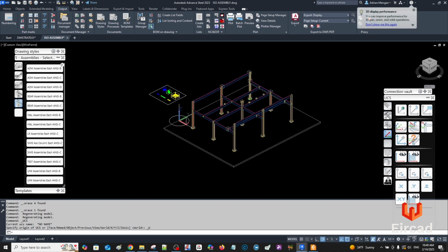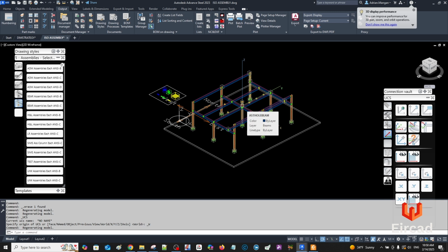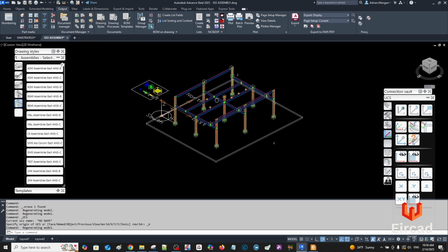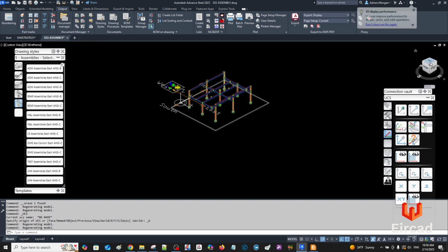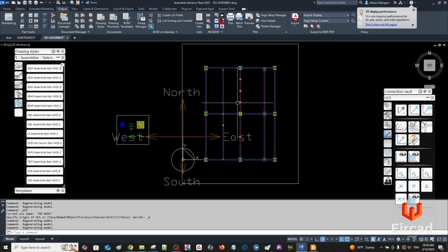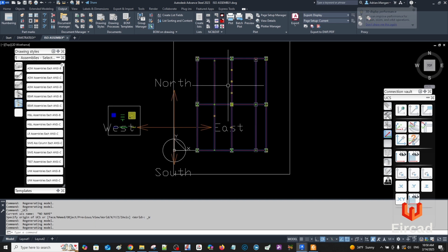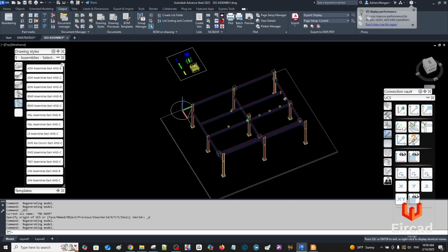So right now I'm going to do some work on cross sections before I do isometrics on drawings, and before I do dimension strategies. Generally in a model, if we go to the top, the intention, I believe, I honestly haven't looked into it in years because I always model from the bottom to the top, from the left to the right, to try and have things come out properly in NC files. I'm not sure if that really matters, but it probably does, right? Because the machine is going to need to know where the start and the end of the beam is, right? So for now, we'll assume we still need to do this.